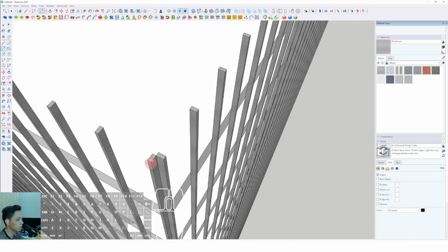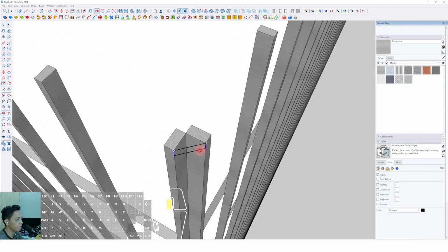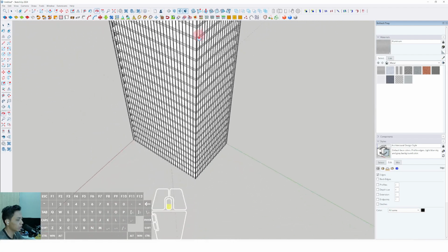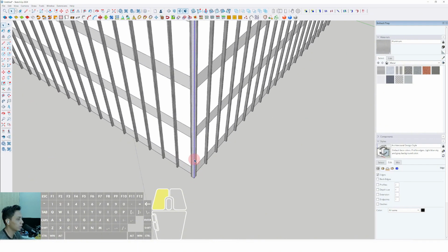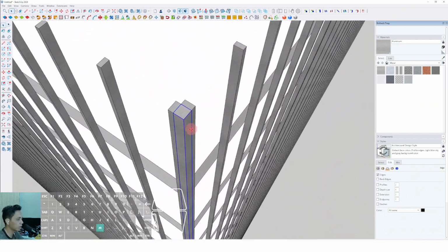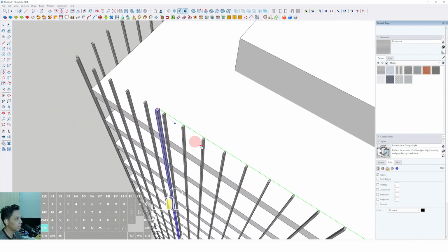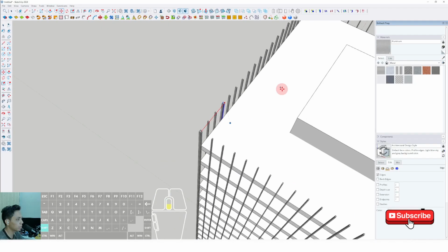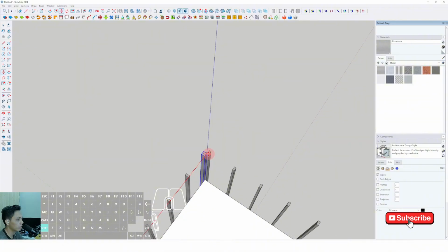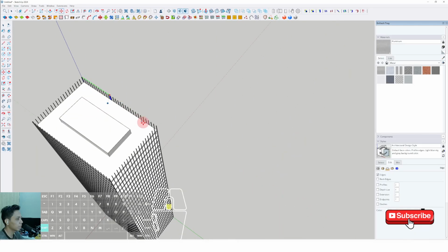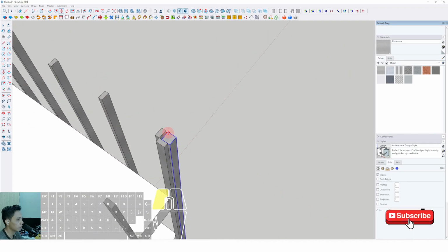I'm sorry, we have to complete this one too, we have to give this the frame here approximately. This is just for a schematic frame, but you have to discuss and consult with your facade engineer, or structural engineer, or architect to make sure about the details and about the dimension. Okay, then we have to select a move, press Ctrl, and duplicate the another position. Okay, then you can select a move, press Ctrl, and place to the another position over there.